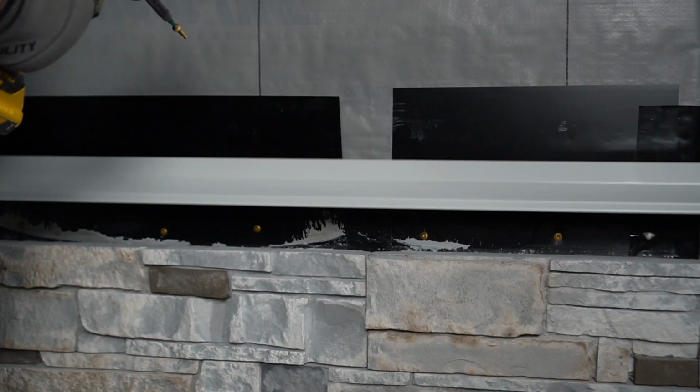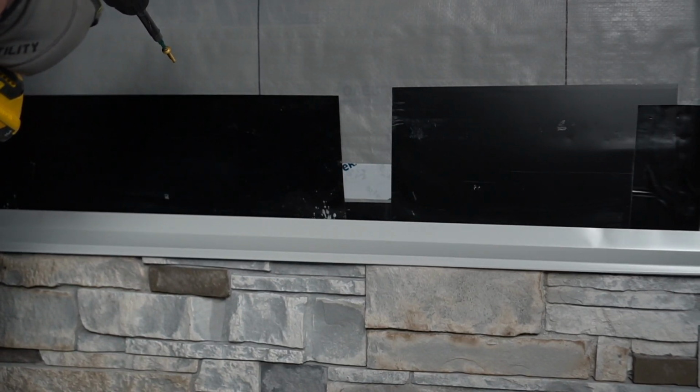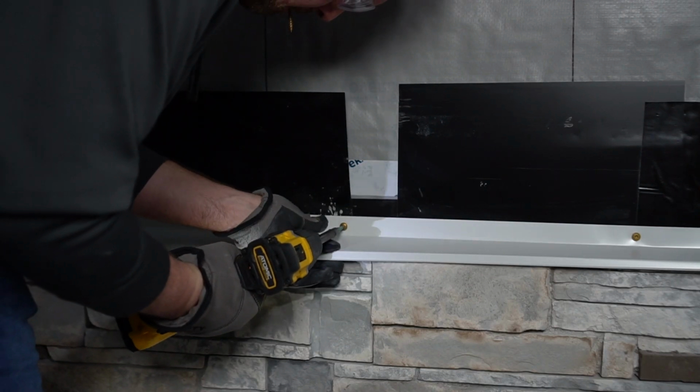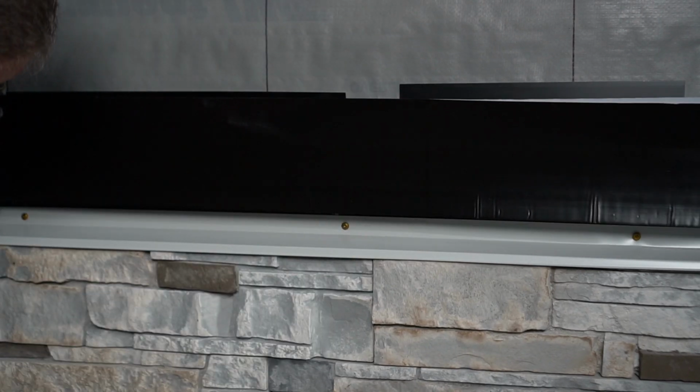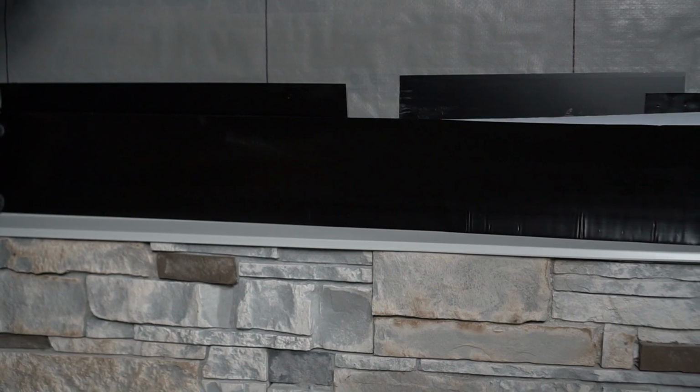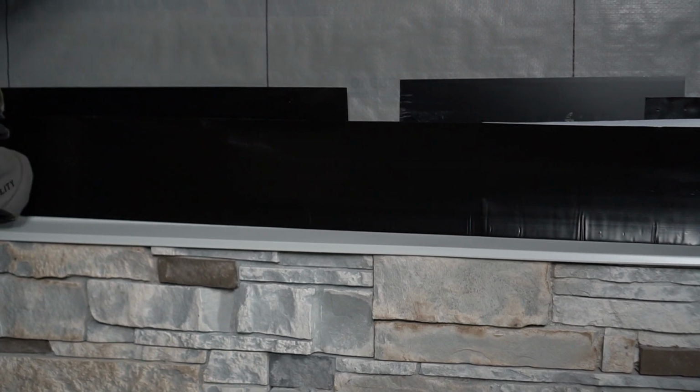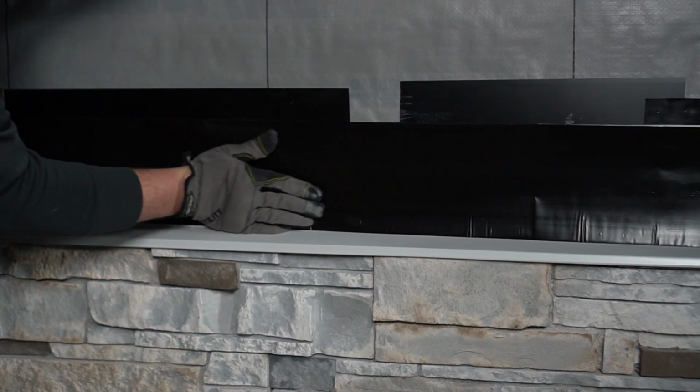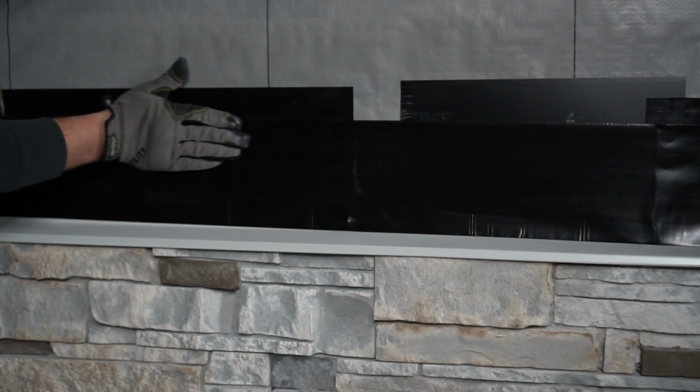Install drip cap flashing over the integrated flashing of the final course of panels or sills after they have been fastened securely to the structure. Apply a strip of recommended 6" SAF over the length of the vertical leg of the drip cap. Install the upper cladding as per the manufacturer's installation instructions.